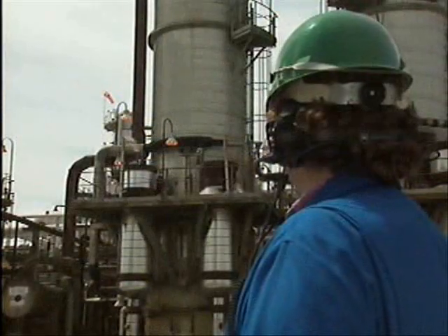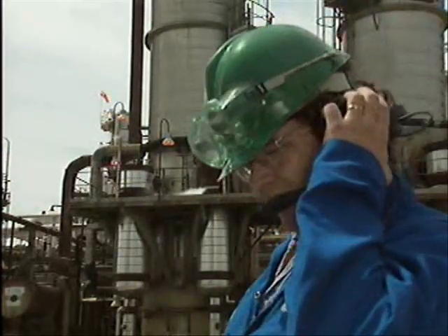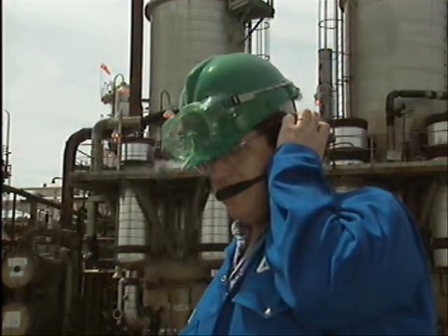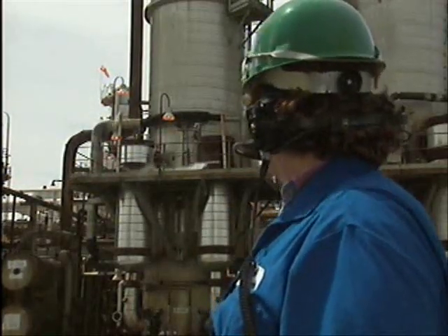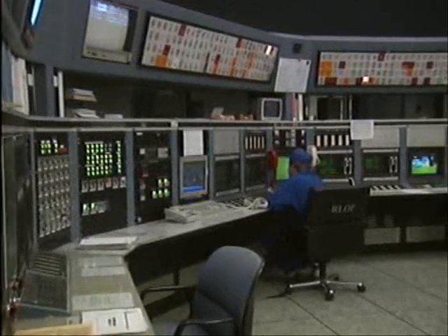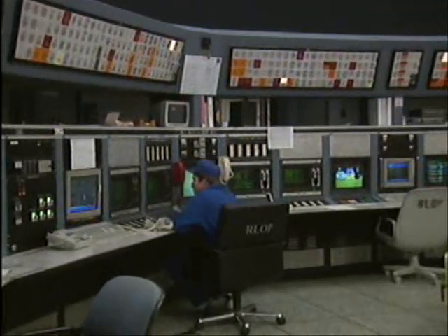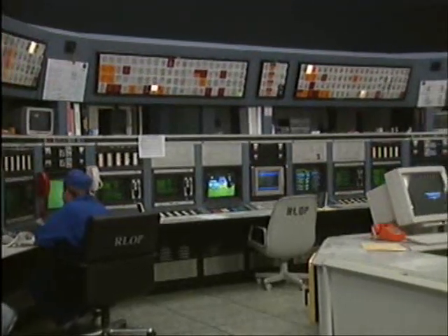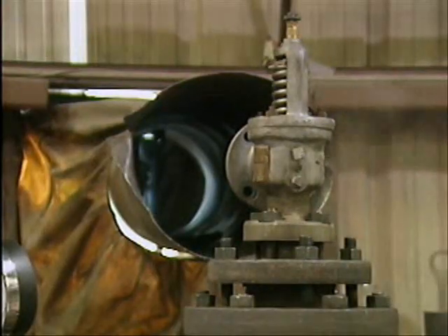properly. But anytime a safety valve is lifted, there's a corresponding drop in system pressure. So before you hand lift a valve, notify the appropriate operating personnel so that they can compensate for the drop in system pressure and keep it from interfering with normal operations. If operating personnel aren't forewarned, when pressure drops as you hand lift the valve, they might take emergency measures to raise pressure or to shut down the system. Such actions could be costly and perhaps dangerous. Likewise, before hand lifting a valve, you must take appropriate personal safety precautions.